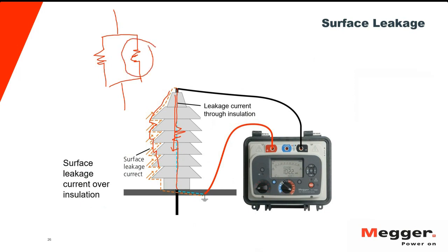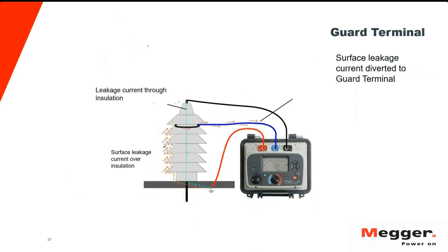Okay, what will happen if you put the guard is that this surface leakage is diverted going to the guard terminal.